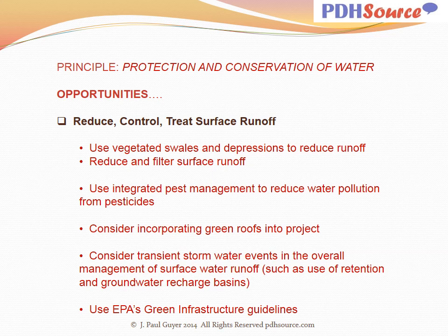An example of where this happens frequently is with parking lots, asphalt concrete parking lots. They just naturally attract grit and scummy stuff, including oil. And so if you can grade your parking lots so that the runoff is channeled through a grit separator and perhaps an oil separator, then that might be a good option for you.